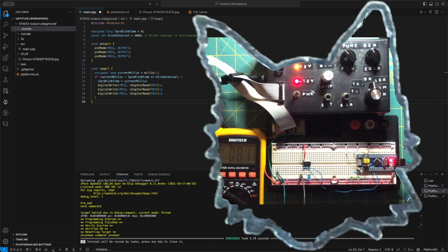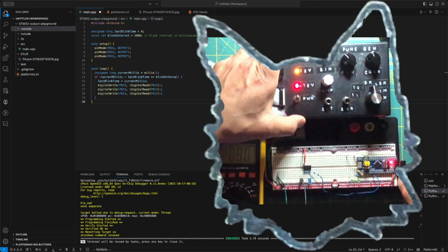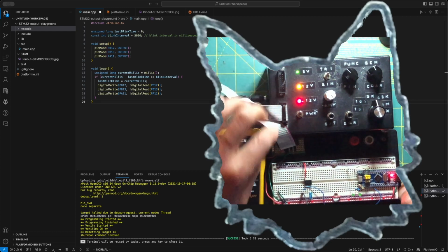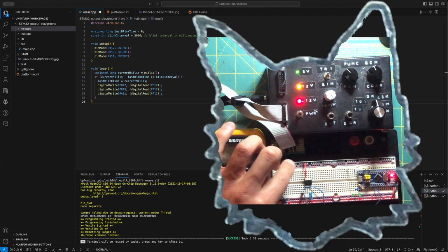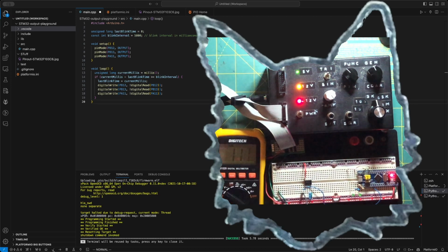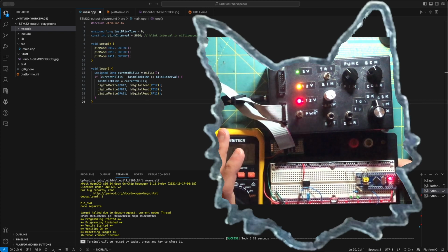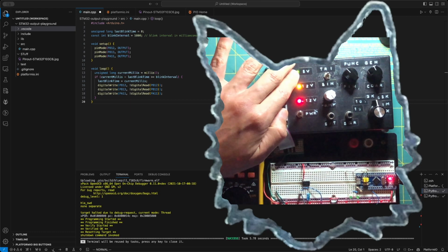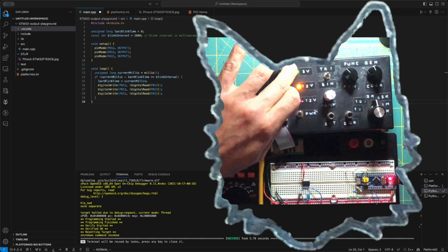the microcontroller. So one thing to note, I am powering this microcontroller from an external voltage source. This actually provides 5 volts, which is what I'm using over here to drive the microcontroller. And I am taking 12 volts for the op-amp. Okay, so just because I wanted to illustrate this, right? So if I was doing this in a project, I would need to get a regulator to regulate from 12 volts down to 5 volts.